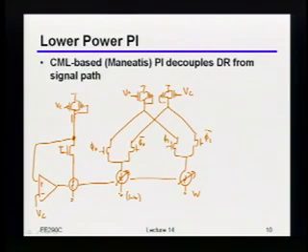Okay, great. Okay, so now, by the way, at least maybe not this exact structure, you may actually flip it over, and I'll explain why that is in 1 second. But this type of structure is indeed what you'll typically use to build a phase interpolator with that edge rate control in it. So now, what's the really annoying thing about this?